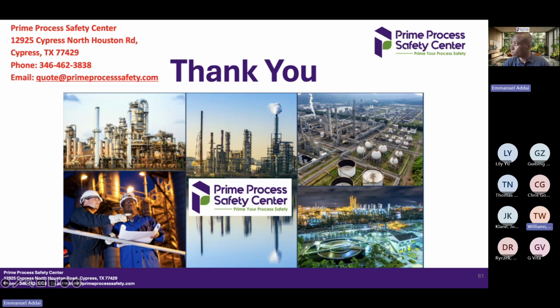And so one of the challenges is, how do you approach this, or what guidance do you give to employers to make sure they have not missed dust that could present an explosion risk by virtue of an incorrect approach to sampling or analysis? Do you know what I'm getting at? Because if you sample your feed, and you don't sample your dust collector, you're going to get very different dust properties. Or if you don't sample the dust that's collecting up in the 11th floor rafters, you might miss some explosion hazards. So I'm wondering what kind of guidance you give around sampling to identify, and then interpret and apply those findings. So thank you very much.